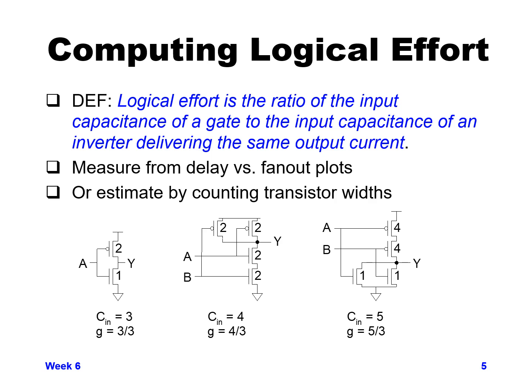So in reality, if you really wanted to get the absolute best value for your logical effort, you would actually do a measurement of your input delay switching to your output delay switching and figure out what the logical effort is by plotting those values versus fanout.